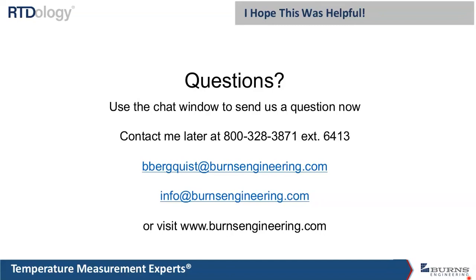Well, yeah, one thing on the M12 and other style connectors, a lot of those will have an IP rating of about, I think it's 67, when they're mated. So they do provide some protection for the inside of the probe. If you have a short extension cable coming from the probe and then the connector, then you've still opened yourself up to potential problems if it sees wash down. But those that have the connector attached directly to the probe will typically have an IP67 rating, which means you can splash water or spray water on it, and it's going to be fine.